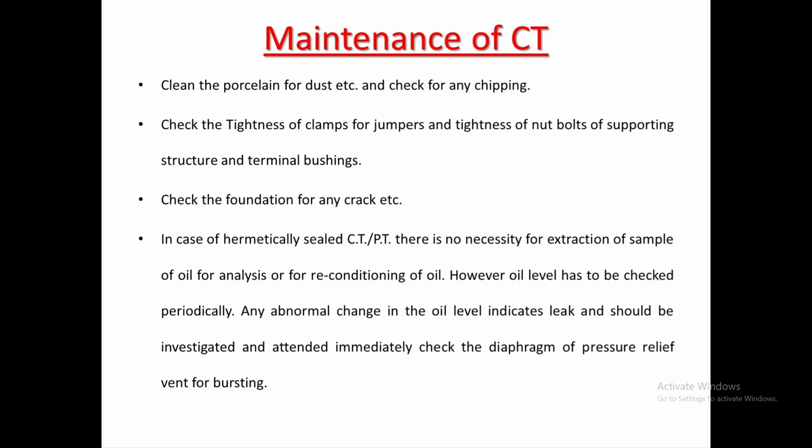So, as we know, this very much resembles our eye. So, we should take care of this input sensing organ, and there is a maintenance schedule. First is the porcelain part, the insulating part, which should be cleaned from dust and pollution, and the tightness of the primary conductor clamp, the jumpers, nut bolts, supporting structure, everything has to be checked.